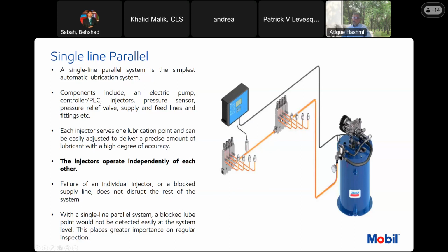But if you lose pressure everywhere in the system, then the farthest lubrication point cannot get enough grease or oil. So the system has to maintain the pressure so it can take the lubricant to the farthest point. That's why these pressure sensors are installed. They monitor the pressure. For example, we calculate that for the farthest point we need at least 2500 psi of pressure. That's how those points at the end would get the grease. So this pressure sensor is set up to detect 2500 psi.